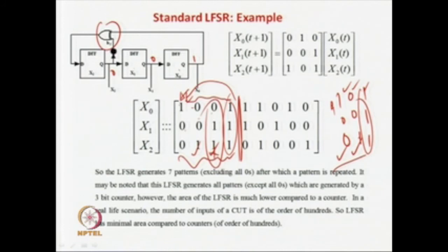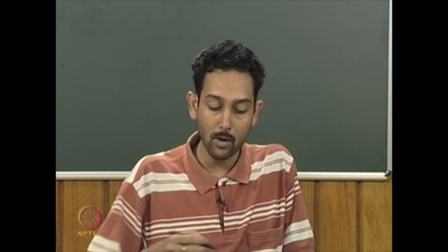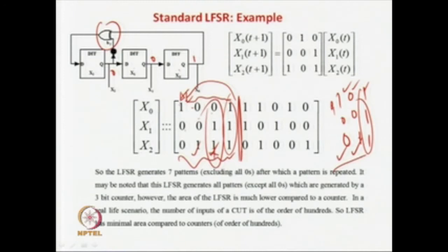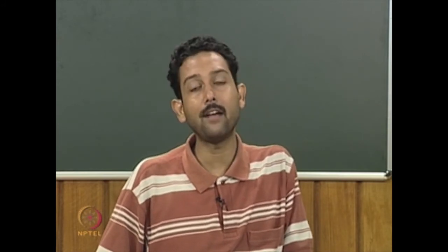So, this is standard digital state machine design, which we always know in digital design. You have to optimize this, and the gate count will be much higher than a single XOR gate. If you go that way, your circuit can be designed and implemented to bring out this pattern and this pattern, but it will take many more gates than required. That is our constraint: we cannot have such a huge number of gates in a test pattern generator because of the BIST area overhead restrictions.